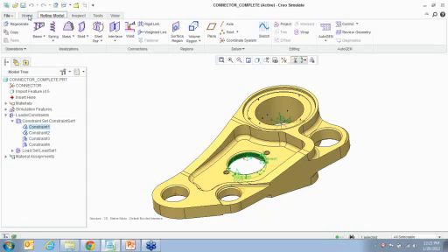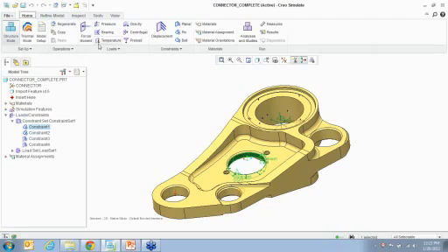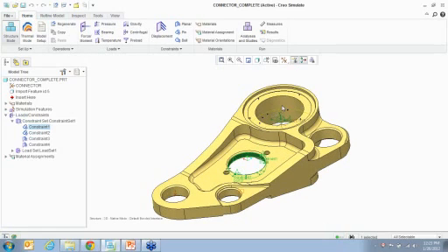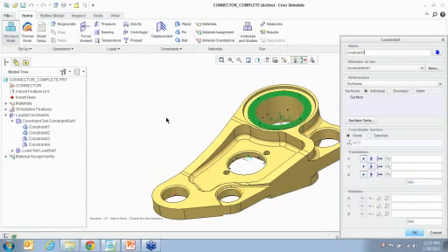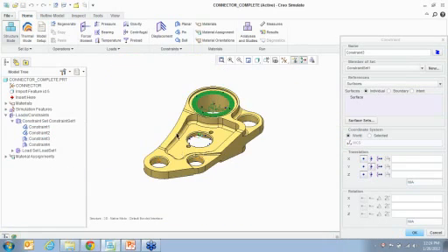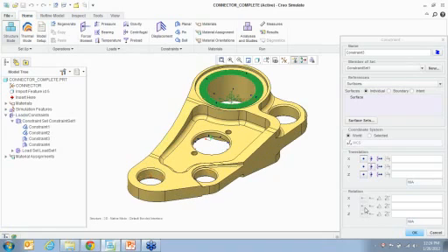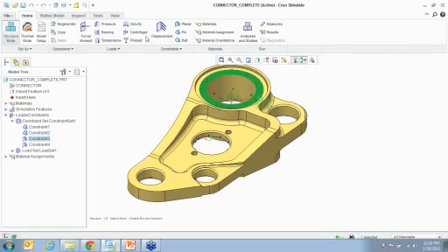You also have another deal right here which talks about the force loads. So again, over here you can see how the rotation is blocked out. So in solids, if you want to create a motion where you want to allow the part to spin a little bit, then you might want to create a pin constraint.